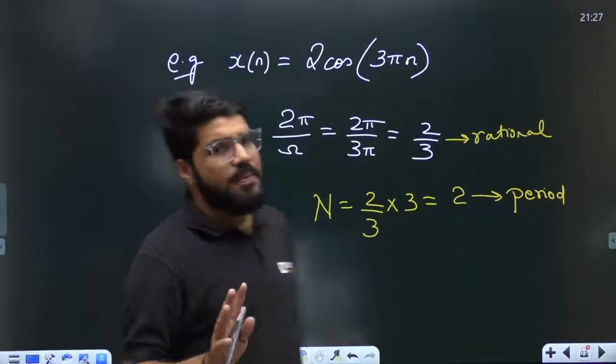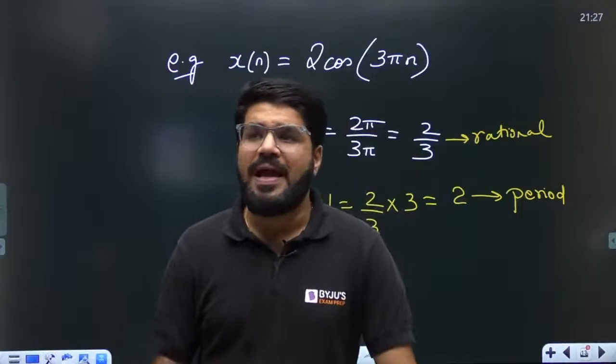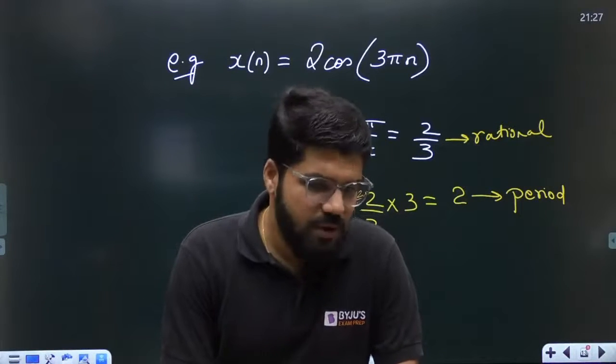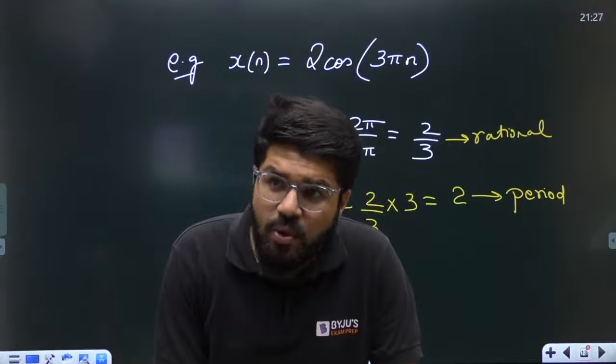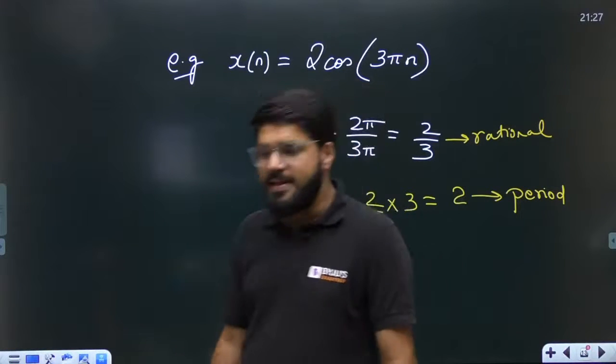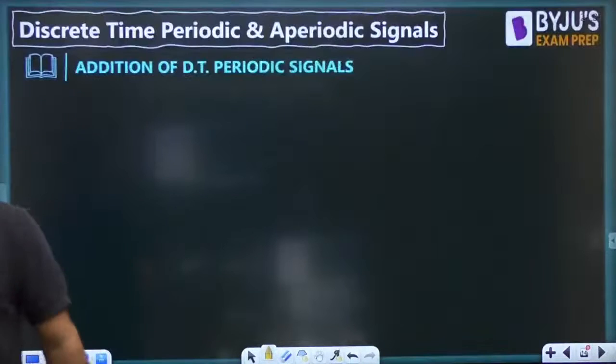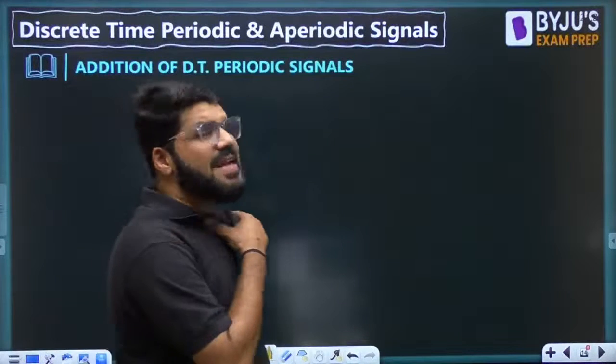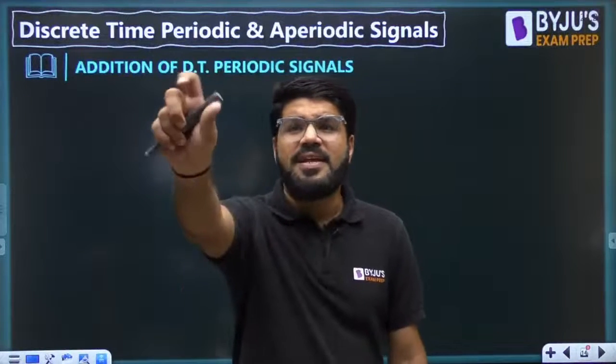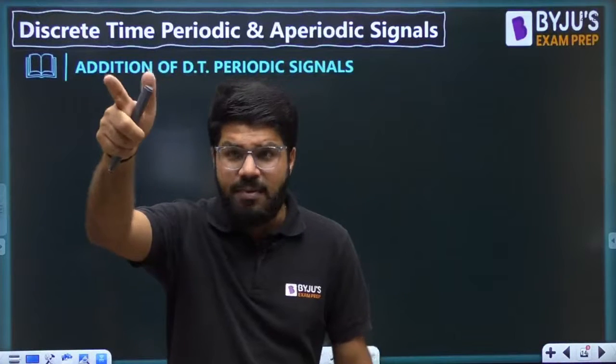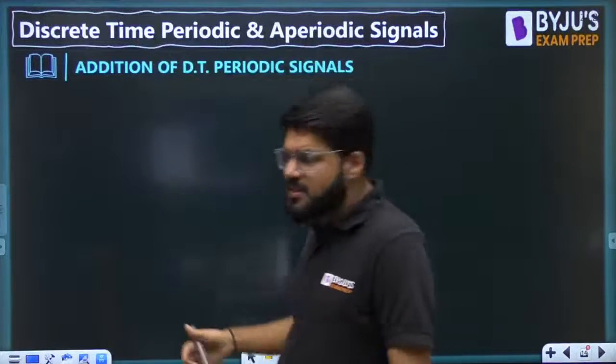So in the discrete time domain, A sin omega n or A cos omega n are not always periodic. They have a condition. But what if I add periodic signals? In the continuous time domain, addition of periodic signals was tested by a ratio test. Remember? T1 upon T2 should be a rational number.